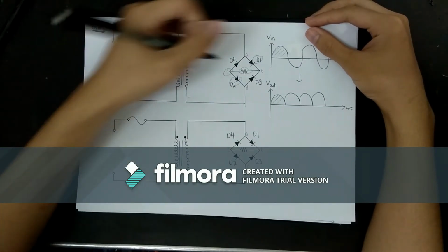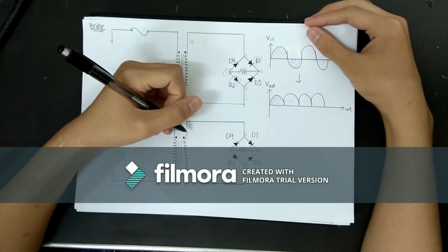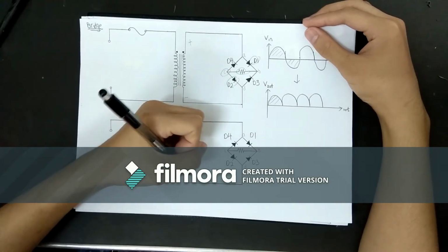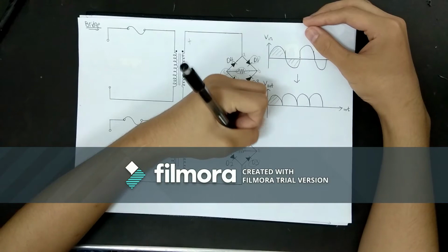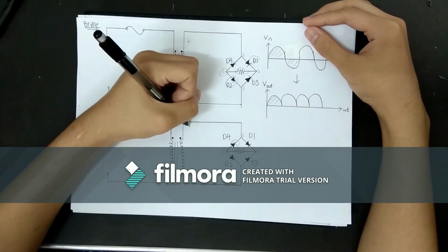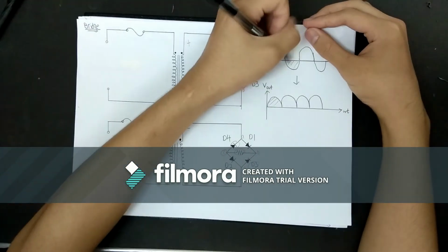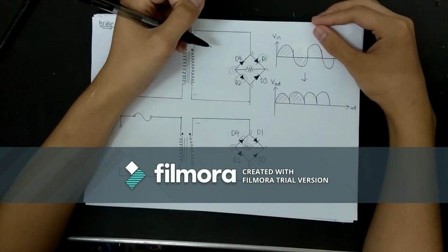And for the negative half cycle, AC flows from the positive terminal to D3 and it passes through the resistor to C and it goes to D4 until the negative terminal. This is for the negative half cycle.